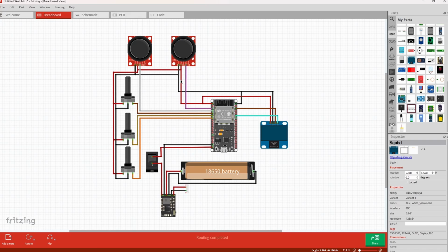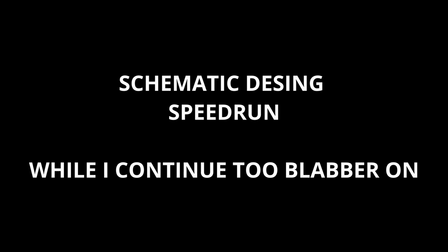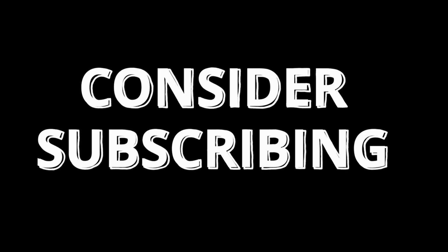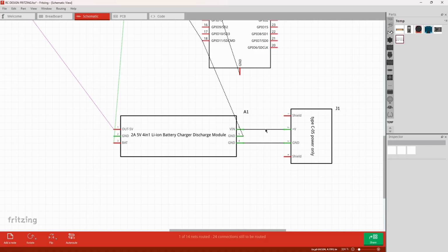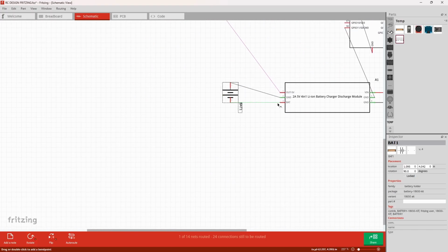Now you might be wondering, okay, it's a remote control, where does the wireless communication come from? Like I said earlier, I'm using the ESP-NOW protocol, I can't remember the exact name anyway, but it's the ESP32 protocol for communicating between two ESP32s through the 2.4 gigahertz signal. So I'm assuming it's using the Wi-Fi. You can't use Wi-Fi while the protocol is ongoing, so that means it uses the Wi-Fi module, which means that ADC2 pins will not be available.